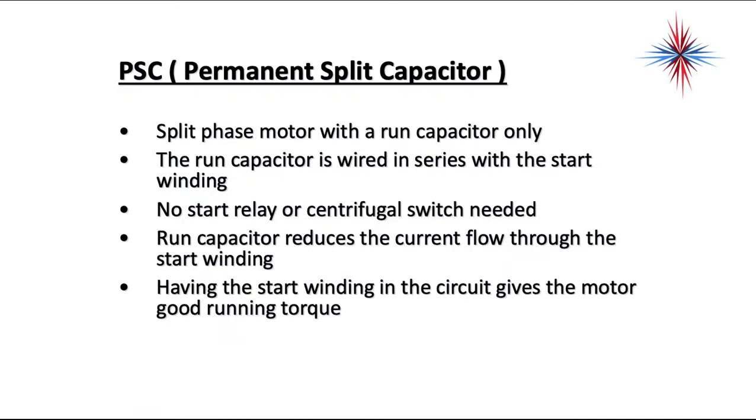PSC is a permanent split capacitor motor. Okay, it's a split phase motor with a run capacitor only. The run capacitor is wired in series with the start winding. There's no start relay or centrifugal switch needed. The run capacitor reduces the current flow through the start winding. Having the start winding in the circuit gives the motor good running torque. It can drive a slightly heavier load with this. This is a very popular motor for both compressors and for blower motors and for outdoor fan motors.